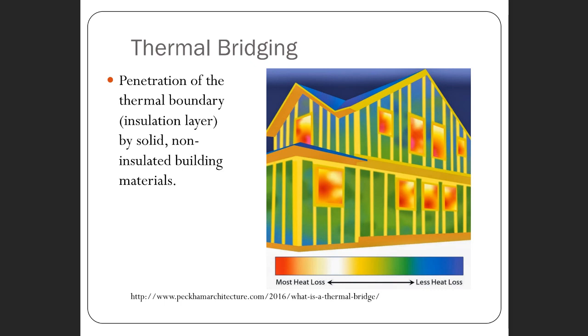So that's part of the reason when we looked at that table a minute ago about the 20 plus 5 or 13 plus 10, that second number is the continuous insulation that's meant to try to address this thermal bridging. So if we're to meet the current energy codes, if we're building a 2x4 structure with our 13 insulation, we need our 10 continuous insulated sheathing. That's roughly 2 inches of insulated sheathing on the outside of our stud wall to help address thermal bridging.